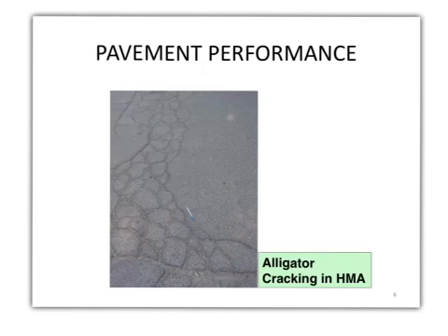One of the major problems when it comes to structural performance is alligator cracking or fatigue cracking. We already talked about this in the previous chapters, but just as a reminder, fatigue cracking really starts from the bottom of the hot mix asphalt layer, and by the repetition of the traffic loads we're going to reach the maximum tensile stress that the pavement can take in tension, and then the crack is going to initiate from the bottom of the hot mix asphalt layer until it reaches the surface.